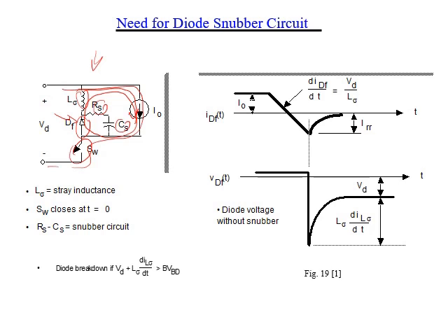Any switch, diode, thyristor, or transistor can be protected by a snubber. Now, for this circuit, when we discussed the operation of the diode, you remember what we mentioned? When you switch off, the current flowing through the diode reduces from maximum current to zero, then goes in the reverse direction and then comes back to zero.